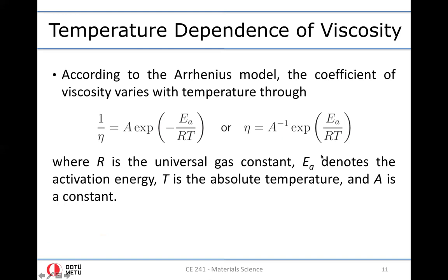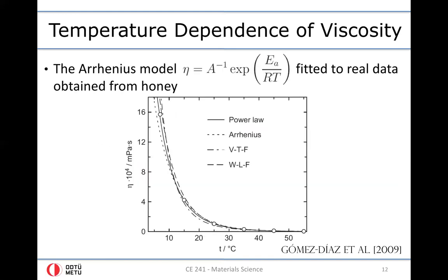Okay, so this expression actually says that as you increase the temperature, due to the inverse relationship, viscosity decreases. So that makes sense, and when you plot this function with respect to temperature, you see such a decreasing tendency.